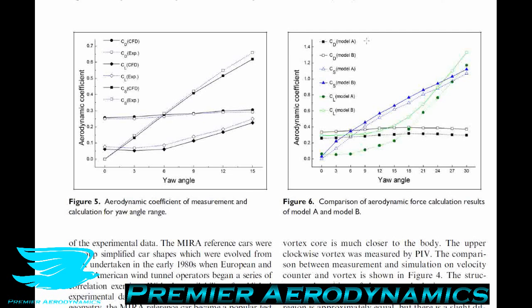But in addition to that, the drag coefficient is also quite bad. The drag coefficient stayed relatively the same across the yaw angles, which is quite surprising, but it was around 0.3, which is not very good at all.